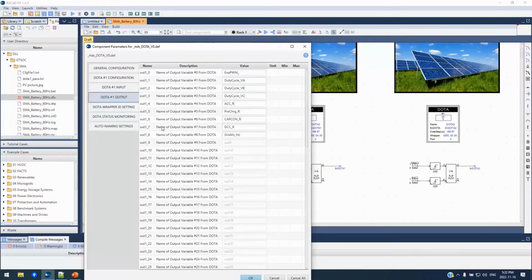And then we have our outputs. These are signals coming from GTSOC to the NovaCore. The main ones here are our modulation waveforms. These get sent directly to our UCM component. We have 4 breaker control signals. We have a frequency measurement signal from the GTSOC. And we have an enable PWM, which in this case is an average value type configuration we don't use.